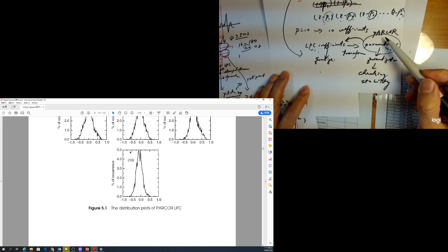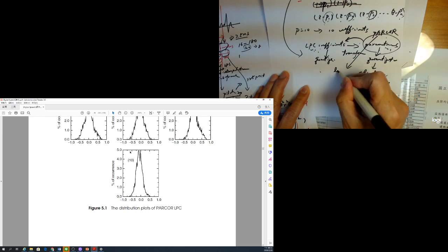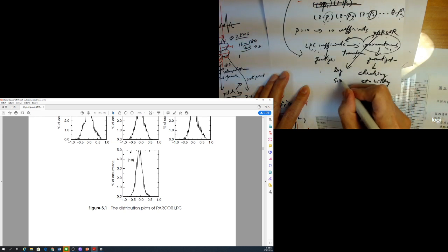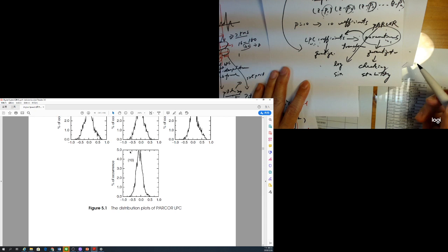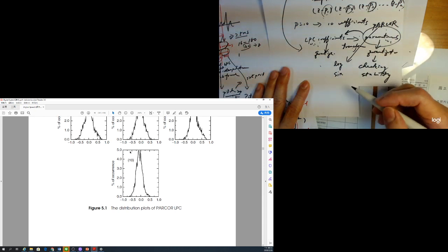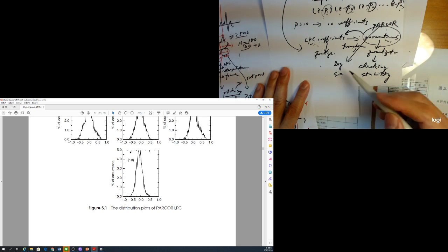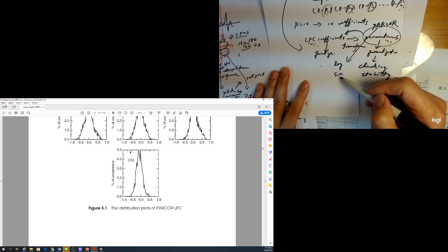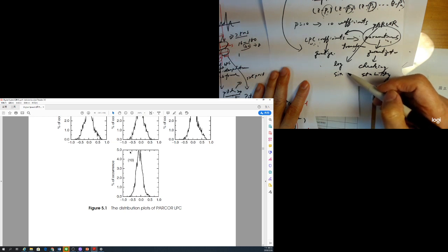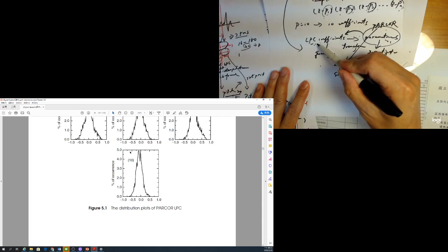Based on the PARCOR coefficient, we can quantize, and we can also do a log scale transfer or a sine transfer. This just changes their distribution and makes good use of the quantizer. Once we quantize and dequantize this data and transfer back to the LPC coefficients,